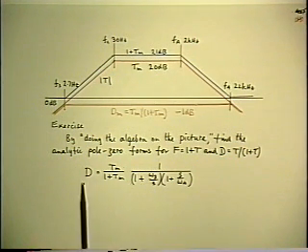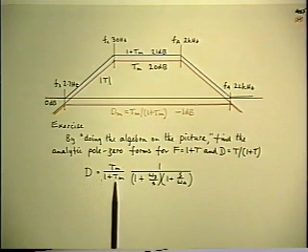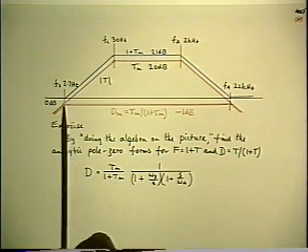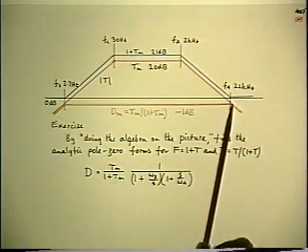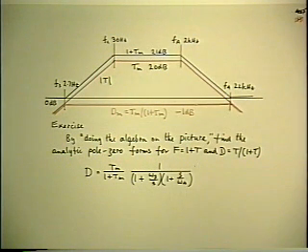And analytically, d is flat at the midband value, and it has an inverted pole at omega 3 and a normal pole at omega 4, which we've already defined in the previous step. Okay, this is the major part of the solution now.